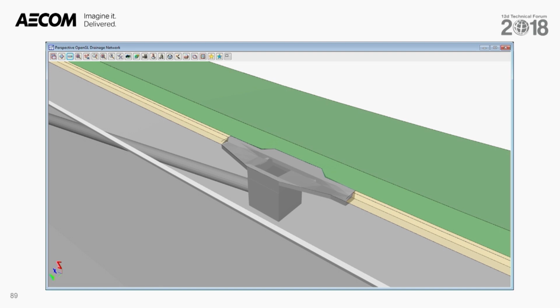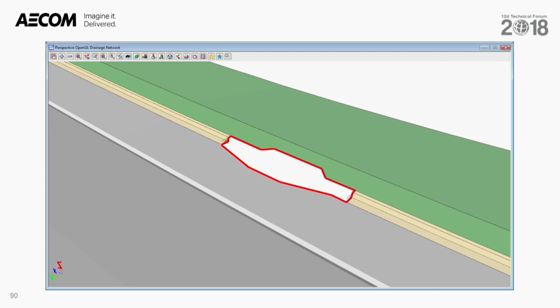We can, however, adjust our road strings to suit a drainage object with a bunch of fiddly MTF modifiers, tucking these away inside snippets to avoid alarming those with a delicate constitution. And you can even create a null string containing the tin boundary attribute to automatically cut a hole in any tin that the boundary is actually included in.